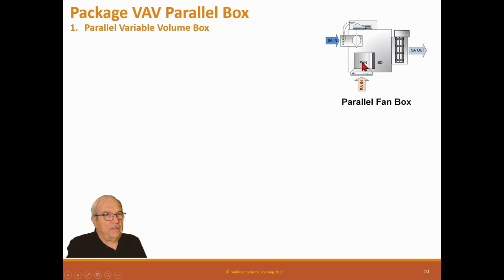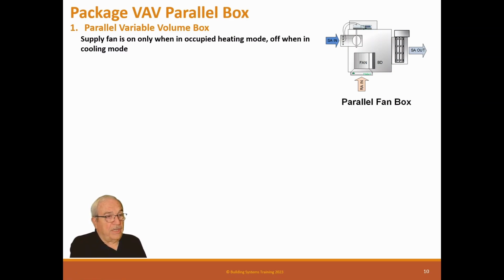It has a fan, but instead of being coupled to the outlet like the series box was, it's coupled to this plenum inlet. So what happens is the supply fan is on only when in the occupied heating mode. So it's not like a series box, it doesn't run all the time. It only runs in heating.